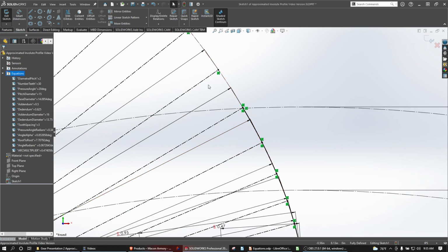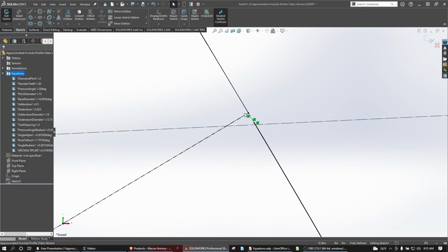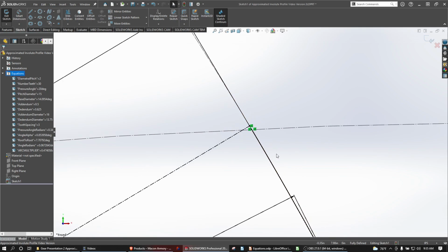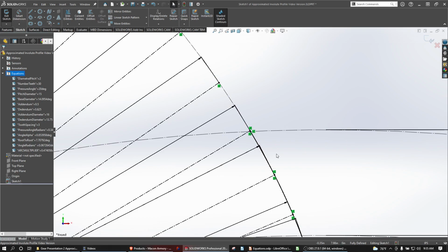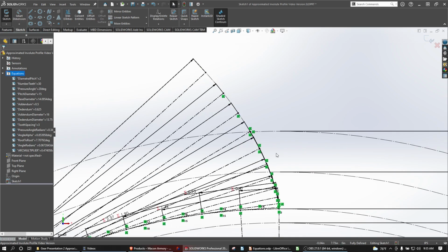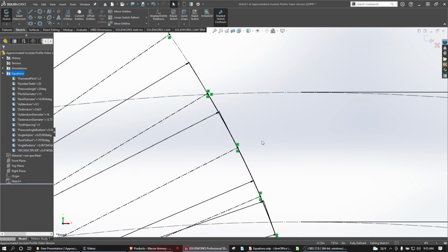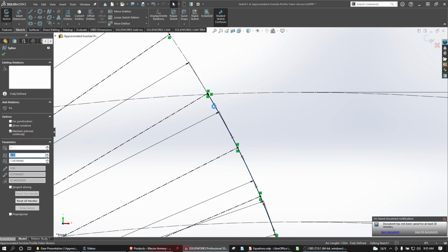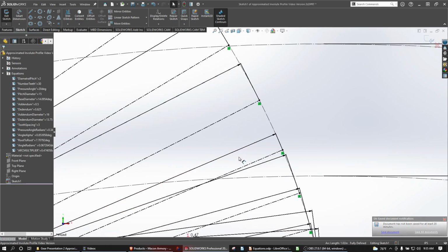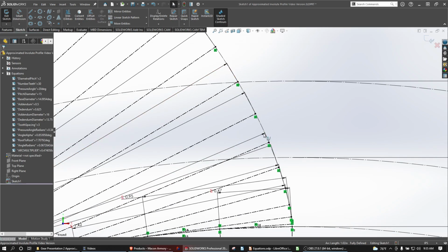If we do that, then these angles will move up or down, right? And so this might move down, and then you're like, well, then I've got the spline that isn't connected to this reference point, and so I'm a little bit more limited in my resolution. And so it can become complicated if you adjust your gear and then maybe have to redraw a spline depending on how big of a change that you make. So I'm a little bit less in favor of this method.